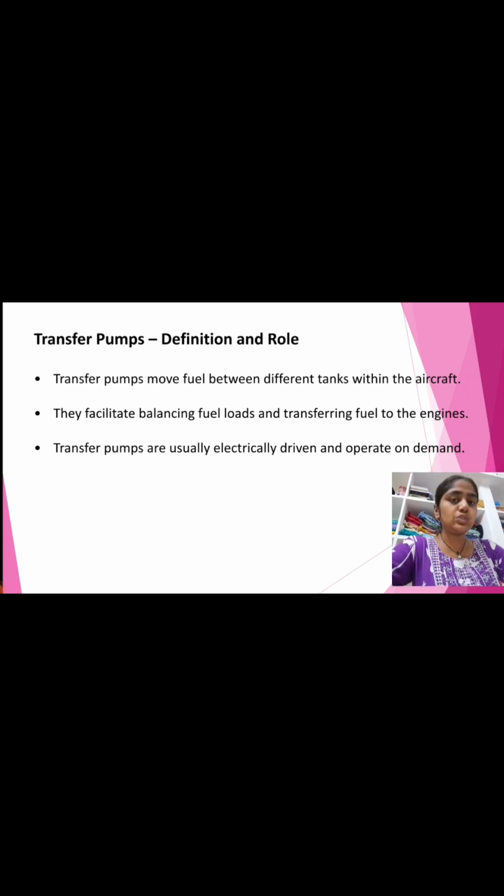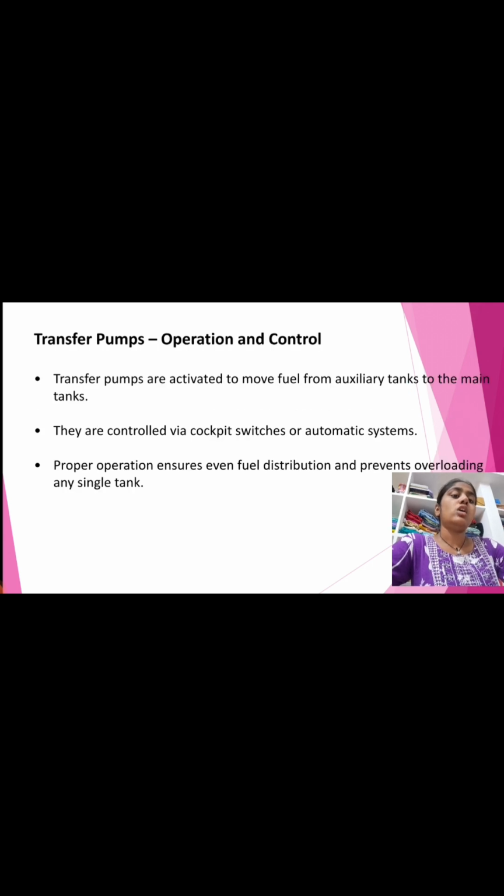Then coming to transfer pumps. Definition and role. Transfer pumps move fuel between different tanks within the aircraft. They facilitate balancing fuel loads and transferring fuel to the engines. Transfer pumps are usually electrically driven and operate on demand.